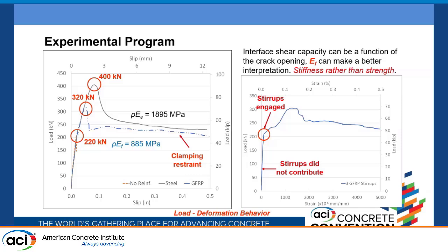But in general, whether or not we have the cold joint condition, the contribution to increasing the capacity is important. In that case, the size of the cracks is bigger. And regarding the second question, if we use epoxy, exactly, that is also going to affect the contribution. Yes, definitely.